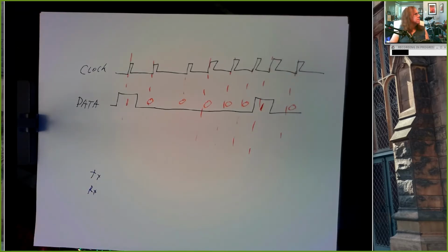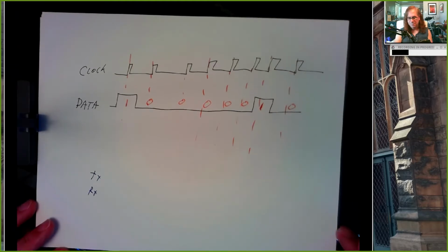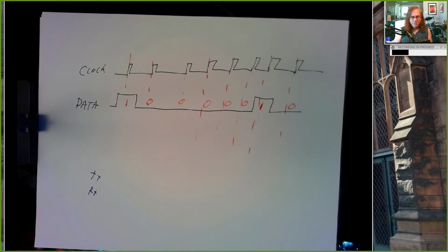So just to make sure that I understand this, the way that serial communication works is there's only 2 lines, and there's a clock line that dictates when it's reading, that there's an input from the serial, and it just reads every 8 bits. It basically, yeah, it really depends on the protocol. So for RS-232, there's no clock line. There's an implied clock, which is determined by what your baud rate is. So both sides have to say, okay, we're going to communicate at 9600 baud. And you both have your own internal clock, so all you need is a transmit line, a receive line, and a ground, which is your common.